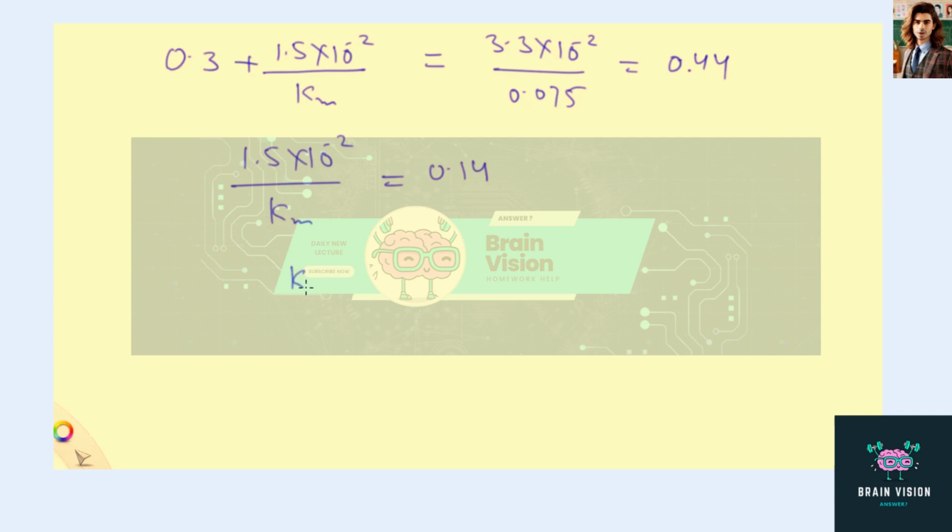So km will get a form of 1.5 into 10 to the power minus 2 divided by 0.14 watt per meter per Kelvin. So finally, the value of thermal conductivity of the insulating material comes out to be 0.107 watt per meter per Kelvin.